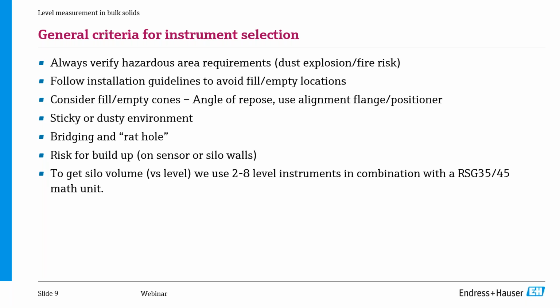For example, we need to avoid installing the sensor very close to the filling nozzle. Otherwise, we can get incorrect and very noisy measurements. In addition, the solid dynamics inside the silo can create a filling or emptying cone, so the location and the angle of installation of the sensor is really crucial to have correct measurements.